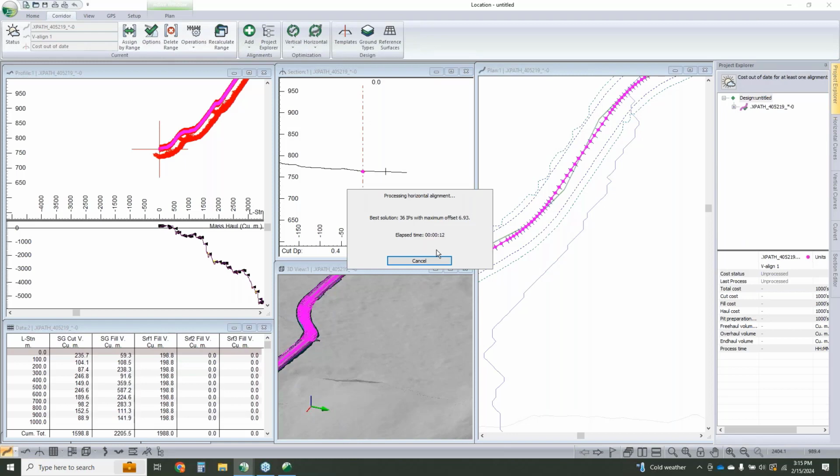So just if you're new to seeing this tool in action, it's going to reduce all those points along the polyline into proper horizontal IPs with their curves applied. So Matt did define our minimum radius, and it's now just fitting it.